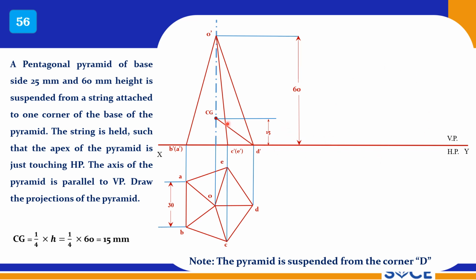So set the drafter parallel to this, and now touching this point you draw a perpendicular line to this CGD line. Once you do this, now this is your reference line, it is touching O now. Now with reference to this line you can measure each and every point of this view, and you can reproduce with reference to this line. You measure from this line and mark from this line. Simple, you can easily reproduce. So that way you can proceed. If you have a line already here, you can measure the distance from here to here.